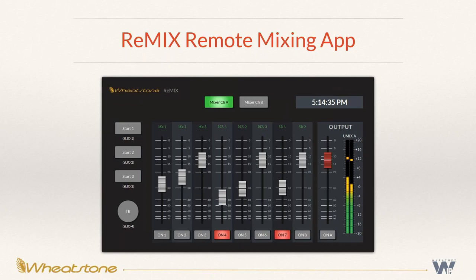Any source on the WheatNet-IP network can be assigned to a utility mixer input, and this includes mics, codecs, phone hybrids, automation playout PCs, other PCs like Vox Pro if you're doing editing and playback. All these are available on the network and now are assignable to the utility mixer. And the utility mixer also gives us 2 program buses, so you can on the fly do a quick mix minus to send audio to a codec or phone hybrid if you should desire to do that.